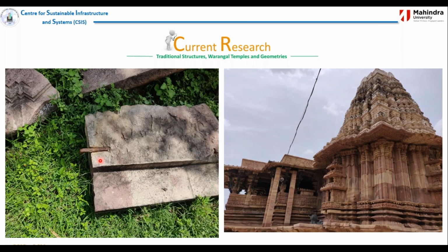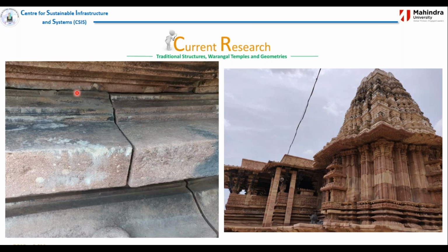These are some stones which we have seen on the side. You can also see the stones here. These are unfinished stones. There are certain numbers, but there were also some unfinished stones seen there. This is more than 500 or 600 years old, but not much history is available on it. And you can see the settlement. Whenever we would like to know the condition of a foundation, only a visual inspection can tell, whether it is a stone structure, masonry or steel structure. What we see are settlement cracks, and these are all attachments of different stones, and we actually saw there is slight settlement of the foundation here.